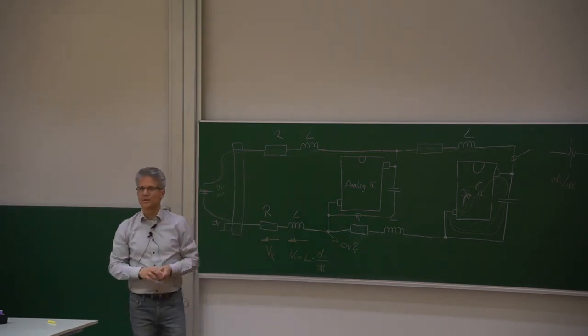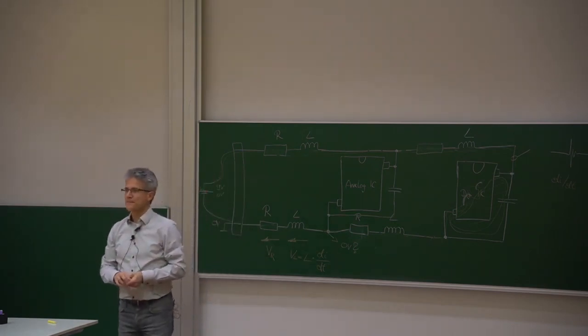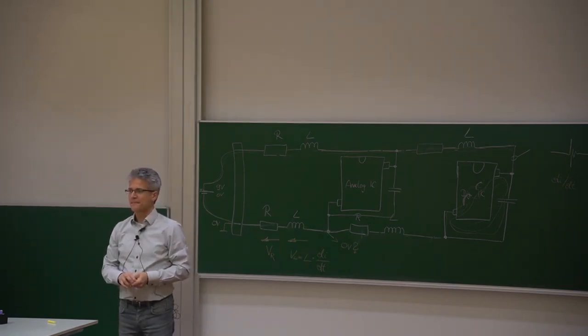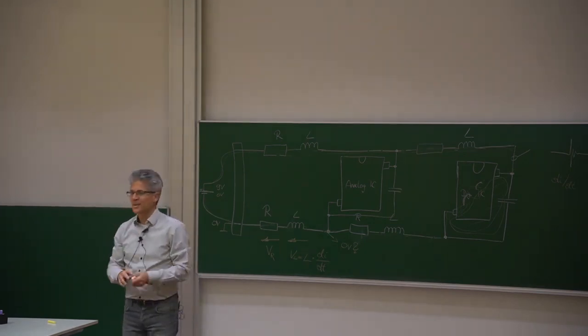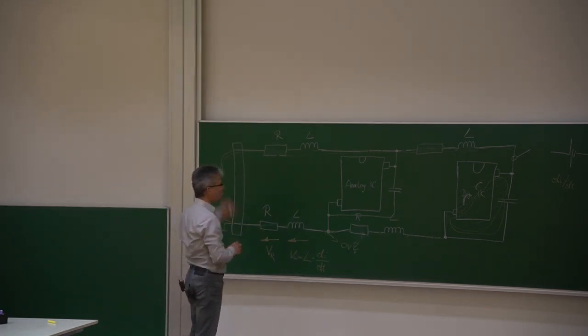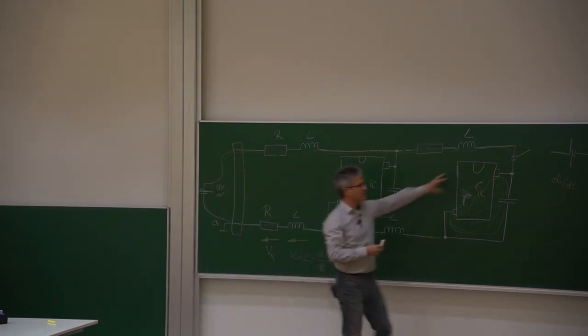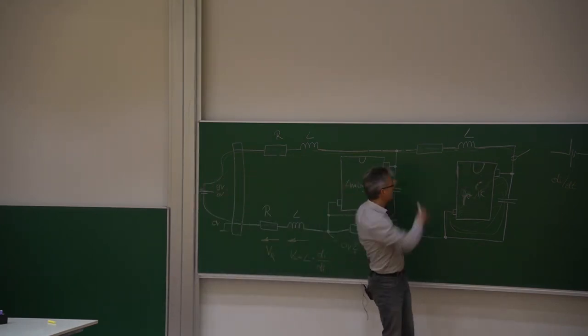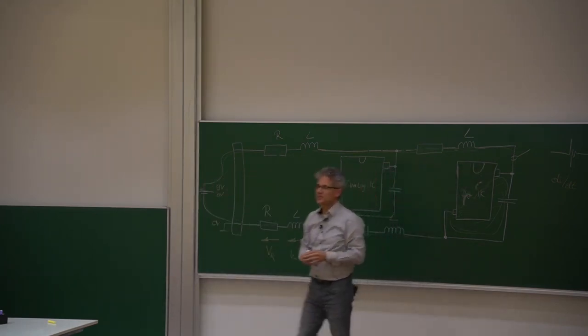Okay, any other ideas? Use a voltage regulator at the input after the battery. Okay, yeah, also possible. After the battery, or maybe also directly here to decouple somewhere, but this is a quite expensive solution.